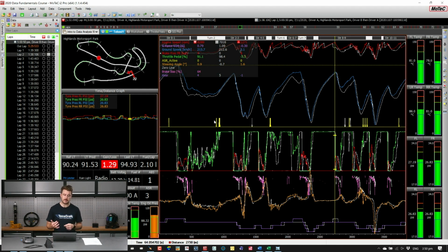So this is the main screen that I would have set up as my telemetry screen when the car is moving around on track. The things that I want to look at are most obvious. And I should say as well, in most cases, as a race engineer, I'm usually more interested in the performance aspects of what's happening. I've usually got with me, working on the same car, a data engineer. The data engineer is more focused on downloading the car, making sure all of the electronic systems on the car are working, the cameras, the logging package itself, and that the sensors are calibrated. In the session, the data engineer is often the one more focused on engine, powertrain or reliability things in general, whereas the race engineer tends to be more focused on the performance aspects. So my screen here is definitely more performance orientated than what you'd have if you're only one person looking at the telemetry, which might be skewed a little more towards reliability aspects rather than just performance.